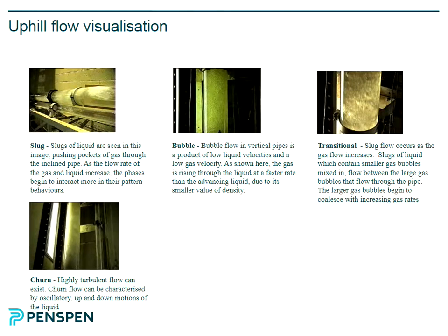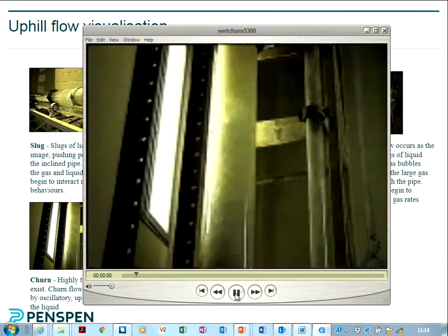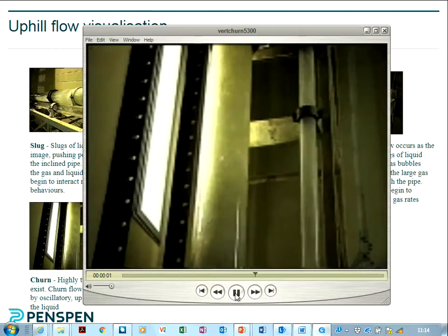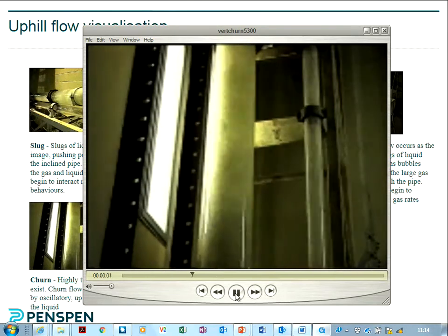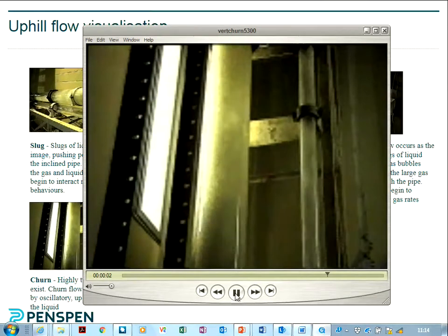So the main parameters here are volume factor and flow rate. If you get a small amount of liquid, high velocity, you'll get mist flow. Large amount of liquid, small velocity, you get segregated flow. That's generally, and then between, you get the slug type flows depending on orientation. So orientation, amount of liquid, and flow rate are the main factors. And again, loads of different examples of horizontal flow maps. You see stratified appears here.